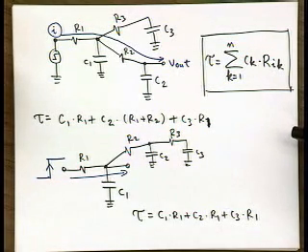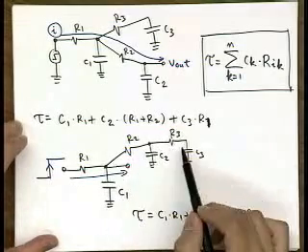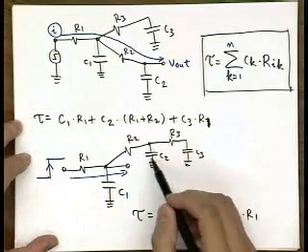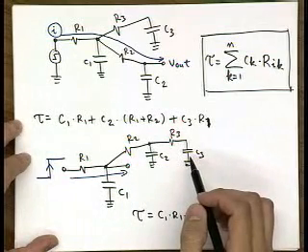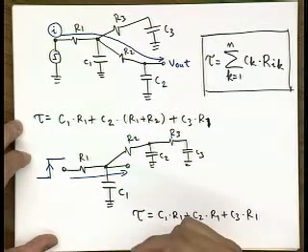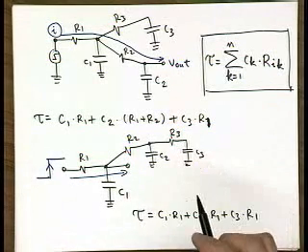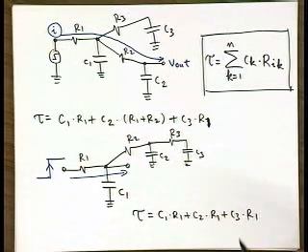So what happens if you want to discharge? Basically, you would also have charge leakage from these guys, because if you start discharging C1, there is still some energy accumulated on C2 and C3, which would be charging it back up. So you really have to consider them both, because that's the energy you have in your circuit. So this formula still holds. It's a good question.